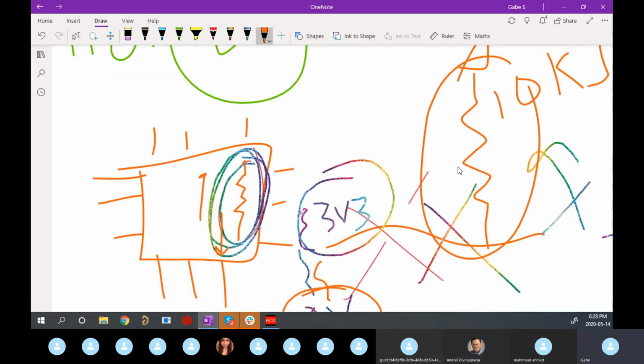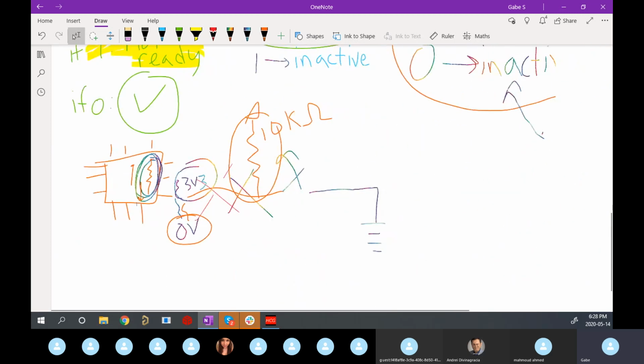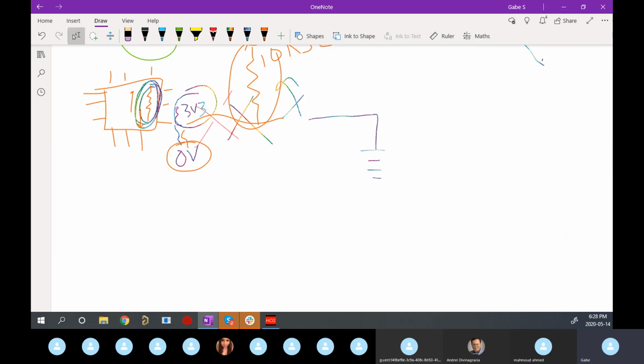Thank you for your question in the chat. We're only referring to that one signal when we're saying that signal is active low. It doesn't mean the whole car is, just that particular signal is, with respect to how the microcontroller interprets it. It means that when it's grounded or sending a 0, it's an active signal, and when it's not grounded, then it's inactive. There are a few other signals that work like this in the car, but it's pretty specific to each one. Thanks for the question, Raphael.